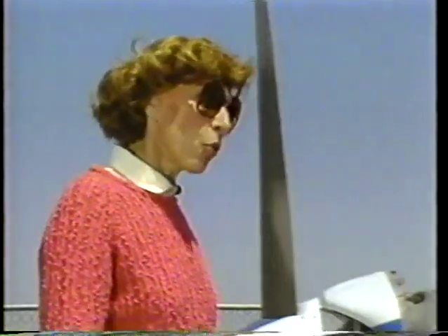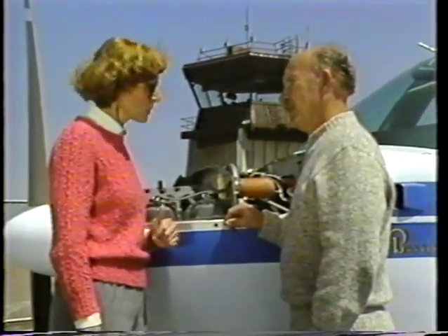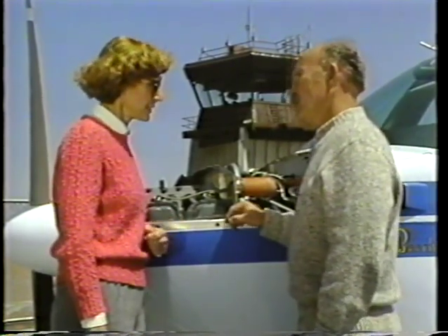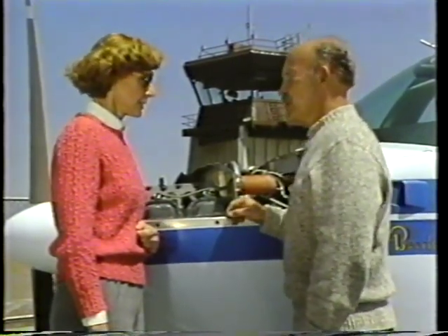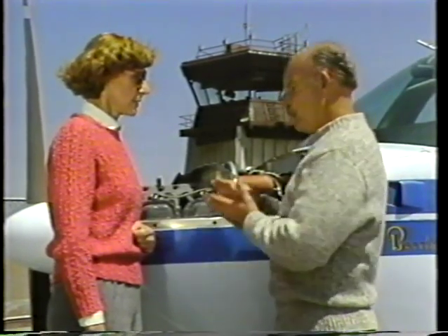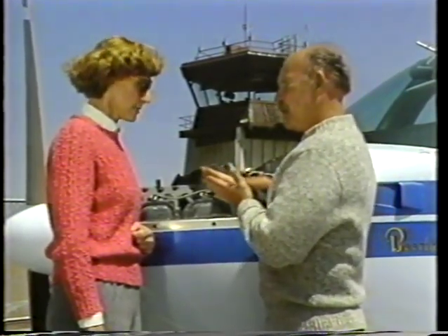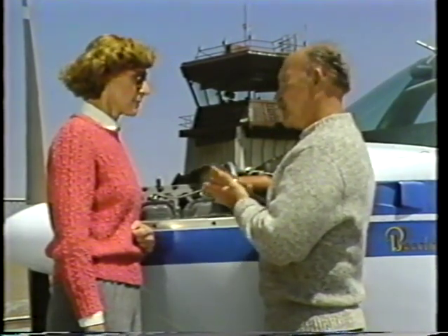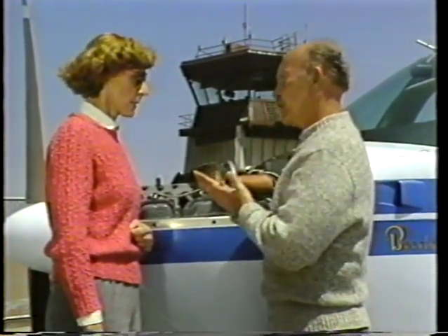Ken, you mentioned how the oil helps to cool the engine. Can you tell us a little more about that and the importance of the lubricating system? Yes, Jeannie, the major function of the oil is, of course, lubrication. The oil is circulated through the engine under pressure, and this helps to prevent metal-to-metal contact of the moving parts. The oil carries away a lot of heat during this process, too.